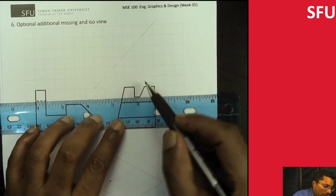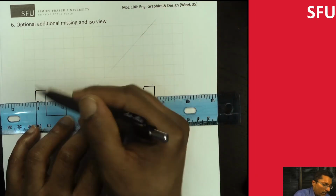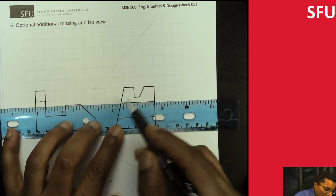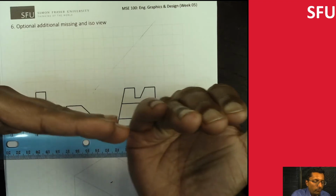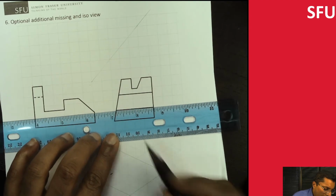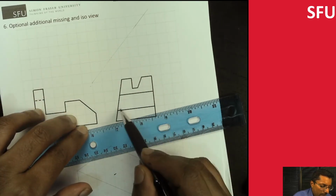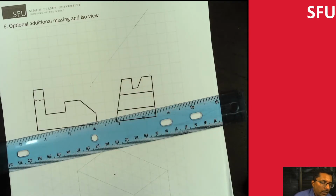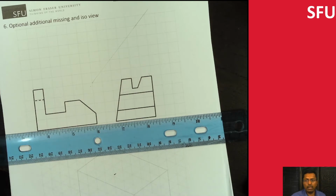That probably forms some feature, and this slanted line doesn't really show up on the front view because it's slanted, and if you turn it over, it's probably just hidden behind this face. So that's that. Let's go a little bit further down. We have a line here and a line here, which means you're seeing an object as lines in two views. If I turn it over, this is probably a planar surface. We go a little further down, and there is a line here and a line here. I can say that this line and this line together form an angled surface, which might show up as a slightly weird shape in the other view. Then we go a little bit further, and this is the view that we get. So this is the object.